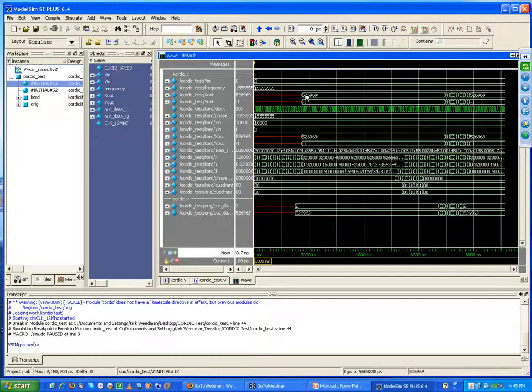So that's from the one I created, and this is this CORDIC.v. This is the one that's in your SVN right now. It did values of 2 and 526,962, which are very close also. So then you'll notice that I held that for a while, and then finally I released and let it start going through, letting the phase accumulator count up, and we're going to zoom in to see all those different angles there.